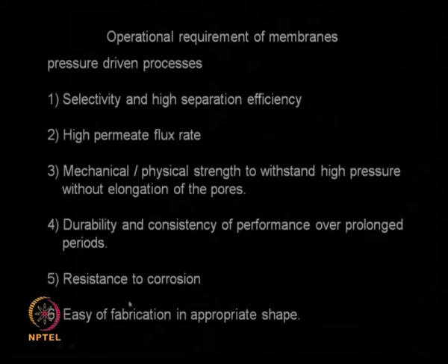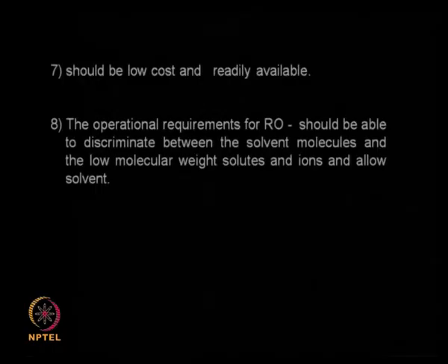It should be easy to fabricate, I mean you should not have a very complicated process and it should be of appropriate shape. I may be using a flat plate membrane, I may be using a tubular membrane and so on, so it should be easy to fabricate in the shape we want to have. It should be of low cost.